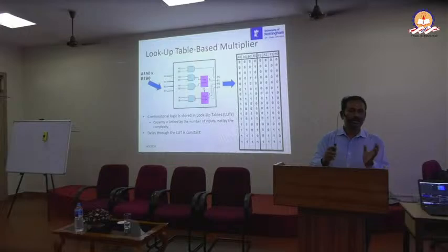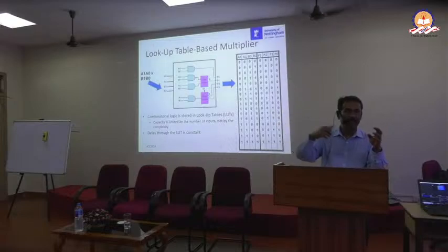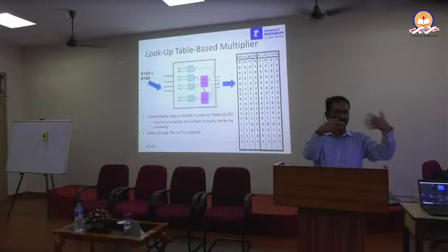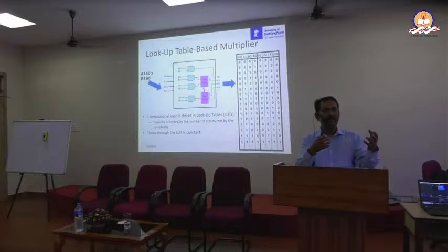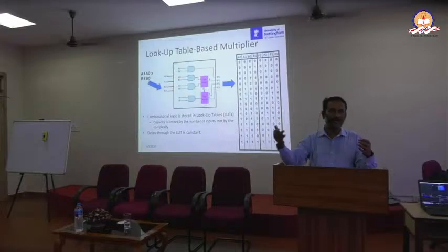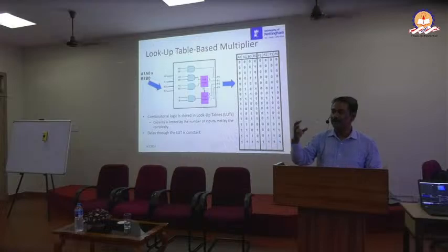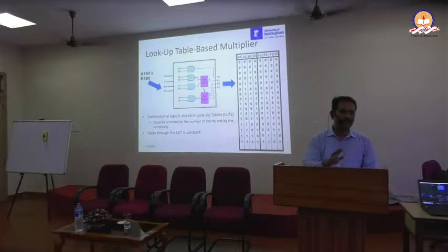So actually when we transfer data from the CPU and fetch the data from the memory, there is a bottleneck now, because the CPU is doing much faster processing, and you need to transfer the data through the copper wire and get the data. So there's a bottleneck because of this copper wire. So what people are trying to do is bring the memory very close to the CPU, to avoid the delay and then increase the performance.